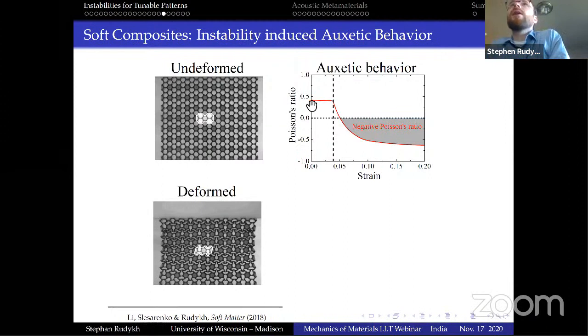necessarily the fact. And now if we look where it happens, that's the part where we have the regular Poisson ratio, for slightly compressible material, because it's porous material, so it's not 0.5, as for a rubbery material. And then we have this buckling, a very prominent point when the material starts to rearrange. And as you can see, there is a whole process until we actually get to the negative Poisson ratio or zero Poisson ratio behavior.